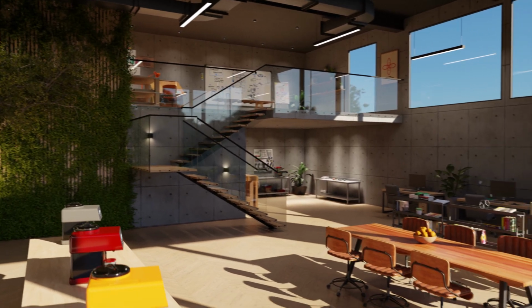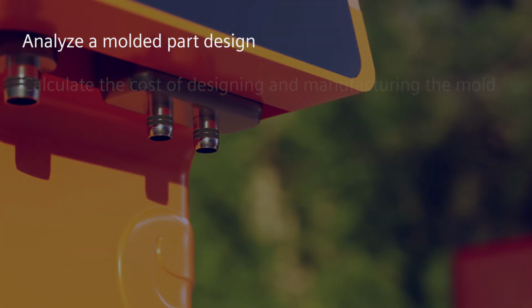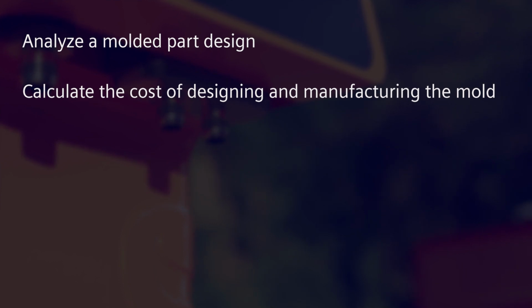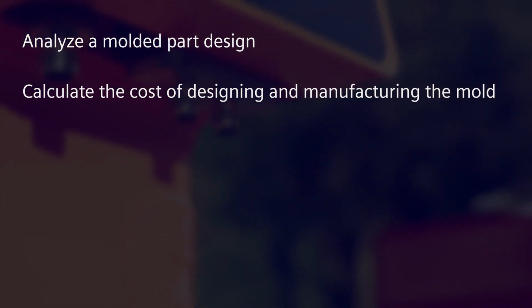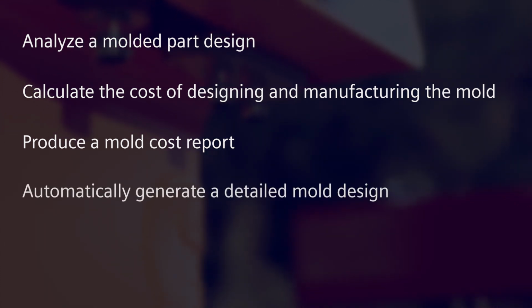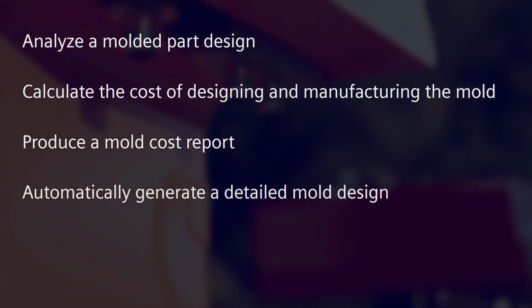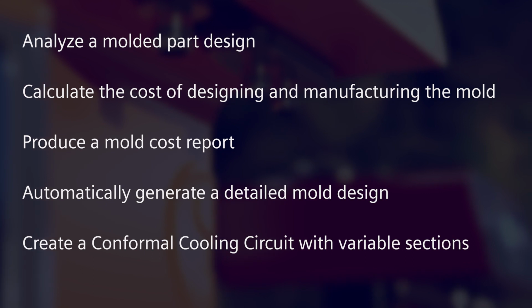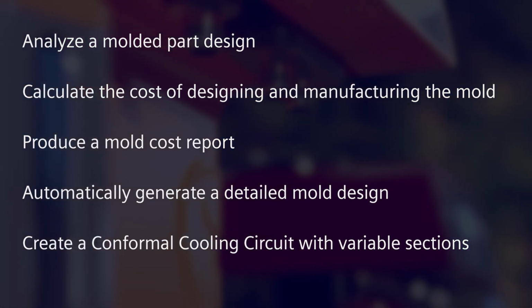So there we have it. We've used Mold Wizard to analyze a molded part design, calculate the cost of designing and manufacturing the mold, produce a mold cost report, automatically generate a detailed mold design, and create a conformal cooling circuit with variable sections. You can imagine how long it would have taken to do all that manually, without NX automating so much of the process for us. Mold Wizard has allowed the supplier to quote their customer faster, while saving their engineers valuable time for more complicated tasks.